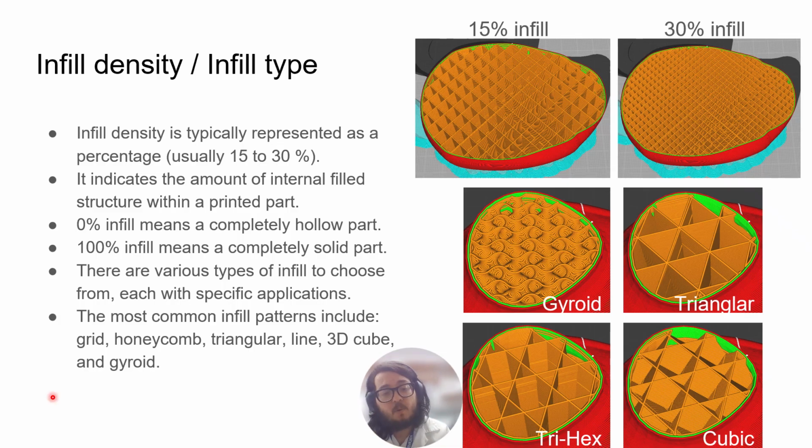But we used to have honeycomb infills. We don't use that anymore as much because they take somewhat long to print. And if you really want that strength that came with the honeycomb, there are trihex infills right now that combine the hexagon and triangles to create this very strong infill while also being composed of just straight lines, which makes it much faster to print.